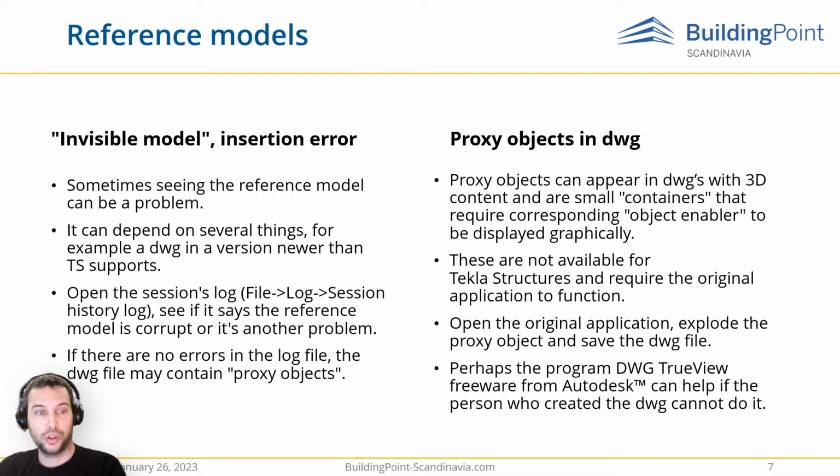You could also find other errors by going to your session log files and looking if there is an error message in the log file. It could be that it's corrupt or something else. If you don't see any errors in the log files, it may contain proxy objects.